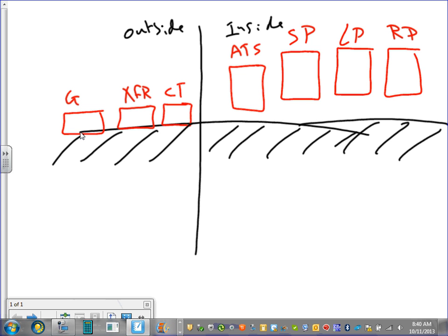Any comments, guys, about this? Any comments about how your riser looks? Could you please sketch them? Like I said, that's how your riser is going to look. So you're going to come from the transformer, go underground into the CT. From the CT, you're going to go underground into the auto transfer switch. From the auto transfer switch, you're also going to go underground to the generator.